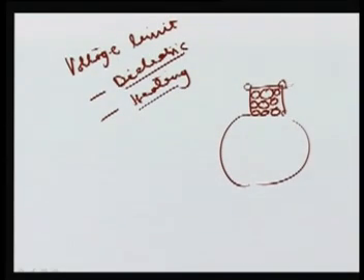So the maximum continuous limit due to the excess flux is lower than the breakdown consideration. Therefore, the limit due to the excess flux is the determining limit. The core flux is proportional to the voltage and frequency.